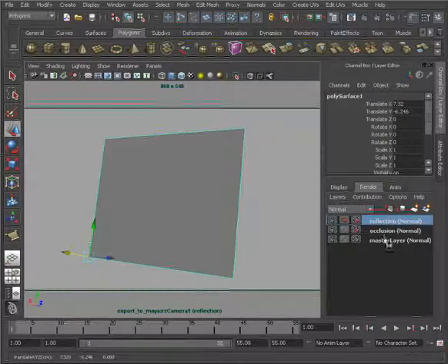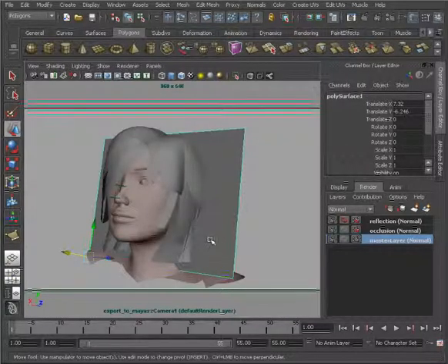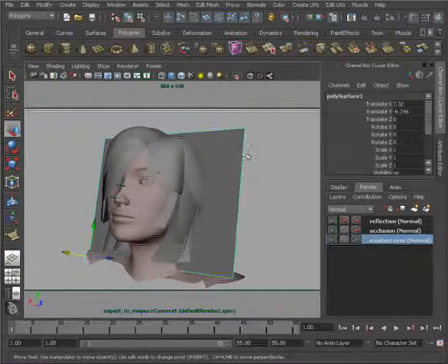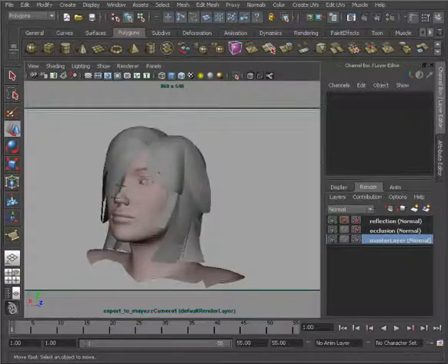And let's also output this as a matte layer. So just going to select this plane here, and let's see, can hit Control-Shift-H. That's Control-Shift-H to bring our head back. And we don't want to see this plane in the master layer, so I'm going to hit Control-H to hide it there.